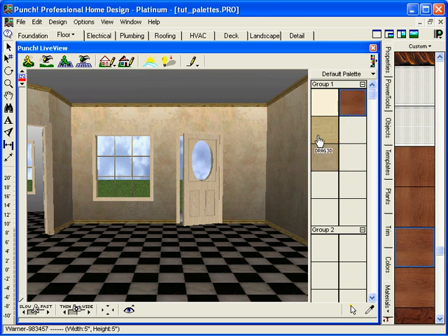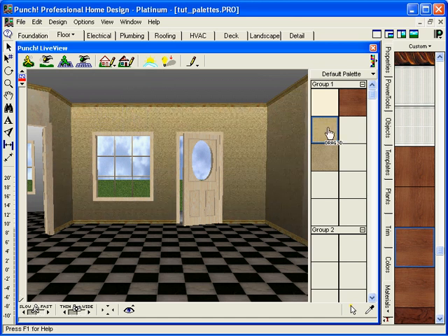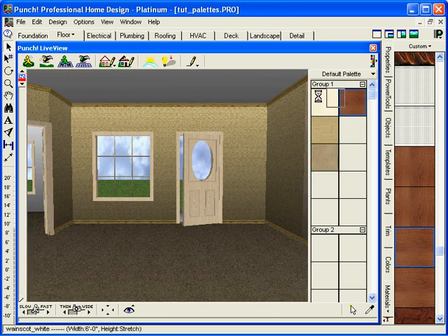And now to use our palette. Drag the wallpaper material from the palette into the room. It's very important to use the palette that you take those materials from the palette space rather than from the actual library. And now we'll drag and drop the wood onto the trim. The palette actually stores the intelligence of which palette space has applied materials to what surfaces in the drawing.